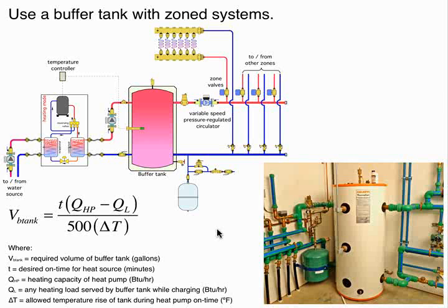minutes. Minimum of 10 minutes. Manufacturers, you could certainly ask them, but if you look at 10-minute minimum cycles versus 5-minute cycles, 2-minute cycles, it could be several thousand start-stops over the course of a season or a year. And as with any device, any motor, the more you're starting and stopping it, the shorter its service life is going to be. So I would suggest 10 minutes as a starting point, and possibly take a look at this formula and maybe experiment even with 15, 20 minutes and see what it does to the volume requirements of the tank. Thank you.